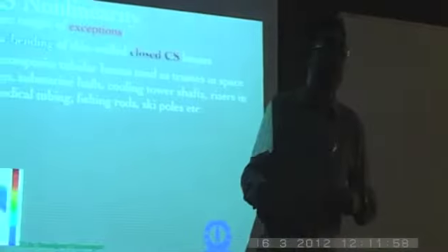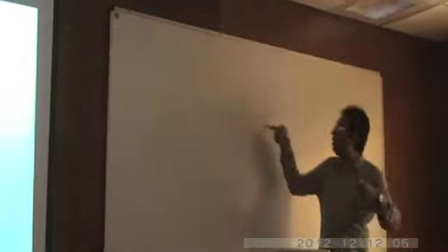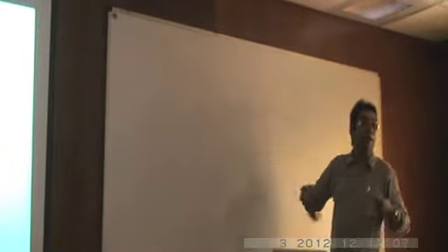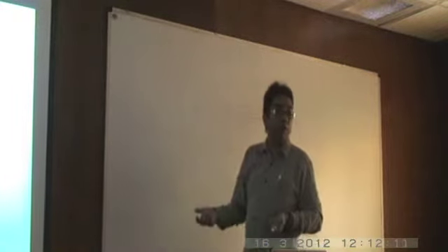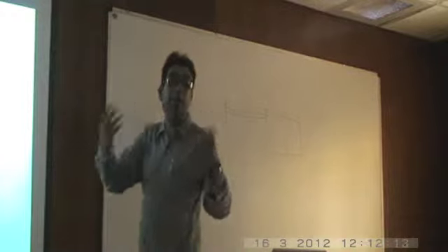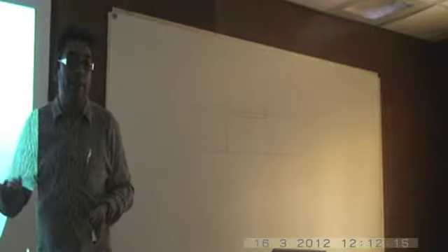Again, in this case it's because most of the bending loads are taken by the spar flanges, and further you have many stringers as well. Those are taking it. So in situations where you have, let's say, a monocoque kind of construction, not a semi-monocoque construction, again it will become very critical indeed.